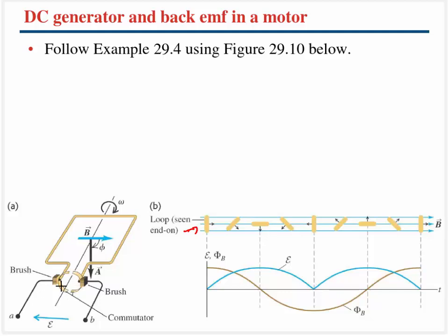But for this example right here, rather than have the two coils connected to two brushes that remain the same, here we have a little gap right there that essentially, when this loop is going to be straight up and down, it's going to switch the terminals such that the induced EMF is always going to be positive. If we were to look at the flux over time, it's going to do the same thing that it did before. It'll be looking like a cosine. The induced EMF is going to only be positive in this case. It's going to kind of hop up and down just like that.